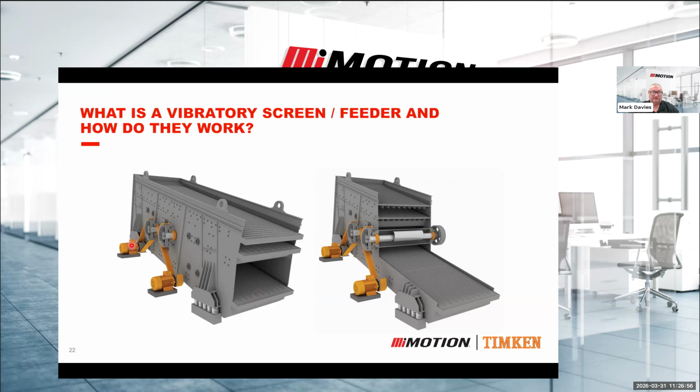But they're basically belt driven. Commonly, this one's a dual shaft. When you look at the cutaway, the shaft has an eccentric section, which causes the screen to bounce up and down when it's in service. And these run at fairly high speed. Again, the speed is controlled by the belt drive, which then gives the amount of movement of the screen that is required for that particular operation. So that whole deck, that whole machine, bounces up and down on a series of springs.